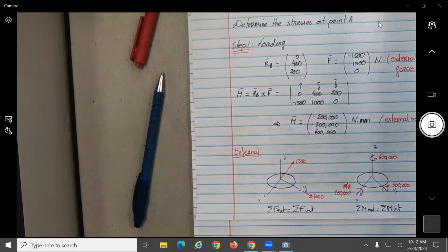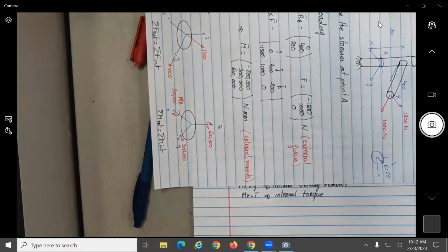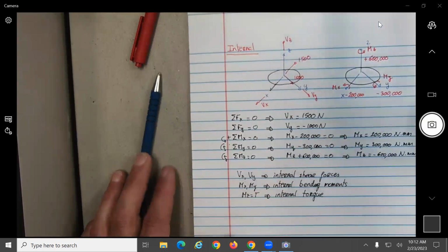Mind you, this could be a cantilever beam. You can decide not to calculate the reactions and just start from the right and make the cut here, so you don't need to find the reactions. Or if you decide to make the cut from the left, then you first need to find the reactions. So in this part, you could do it both ways. Personally, I do the first, to tell the truth, but if you really want to use the equation, this is what you need to do.